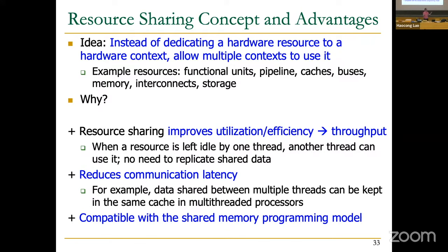Private caches are essentially replicating pieces of that memory locally next to the processor, right? So, from a principled perspective, it's not compatible with that model. Of course, it's compatible in the sense that this is all under the hood, right? You're still obeying the shared memory programming model from the software perspective.